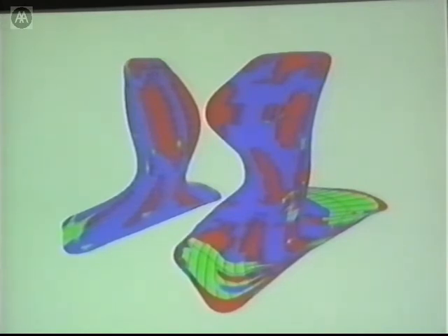You can either try to put a preference on a manufacturing process, and you could say, okay, we need to get rid of certain types of curvatures in order to produce everything from flat sheet. Or you could say maybe there's a differentiation in the manufacturing process simply by knowing that there are some areas which can be made from flat sheets and others that cannot. So it's a low-level analysis that allows you to assess these kind of things and make them design criteria for a further approach.